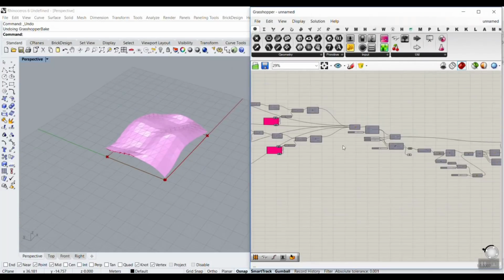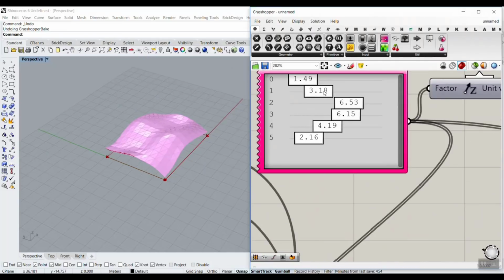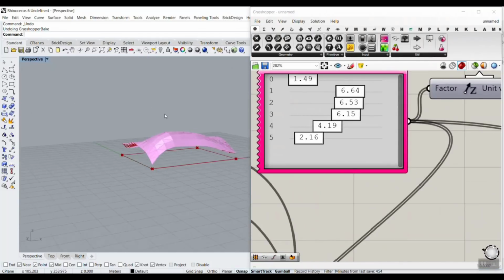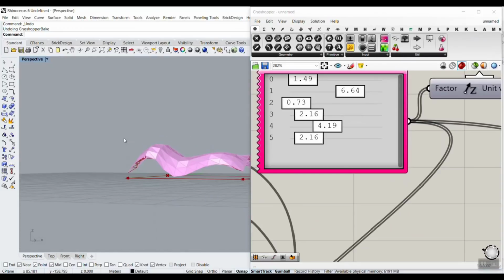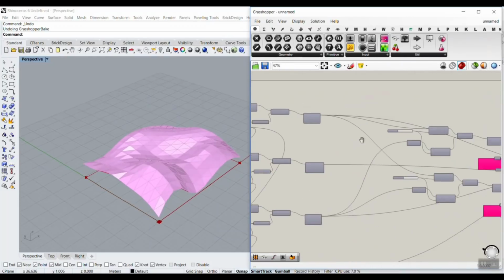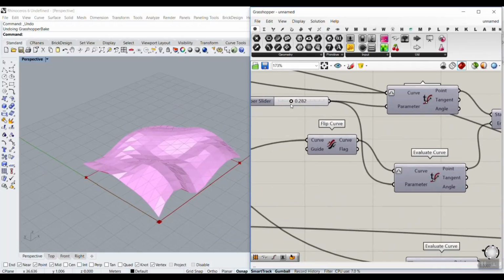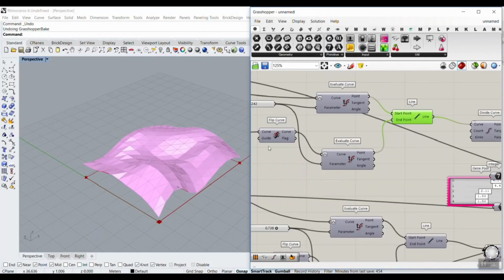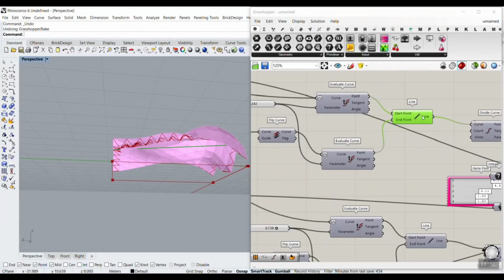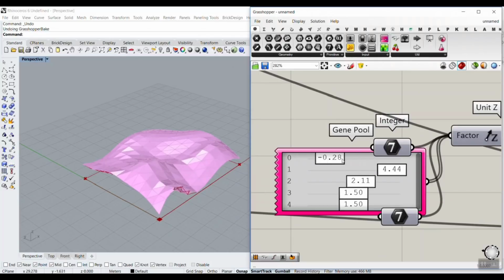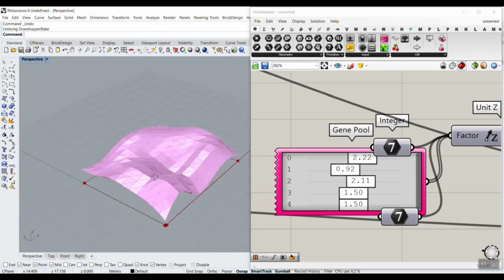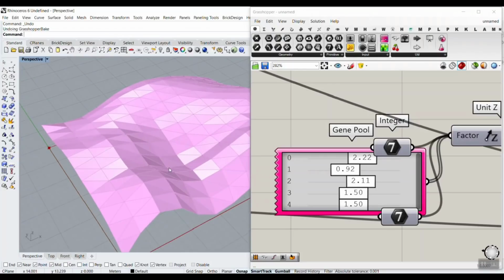We can change the form. So you can see we had also 2 sections here which we can change the location. Let's just turn this line on so you can see that we are producing the section here. Okay, and then we can change those heights too, if we want to have more control over the surface and produce a complete NURBS surface with panels.